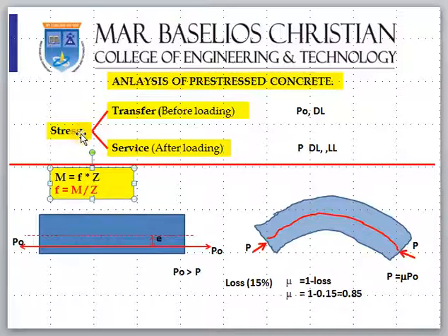Now coming to the stress, I told you already, there is a transfer stage before it is getting loaded. Another thing is self-weight after loading. Remember, in prestressed concrete, see this figure. We have these tendons, or reinforcement, which we call tendons. We stress them, stretch them, pull them to the maximum limit with some force. Let us say this force is P0, and we cast it.